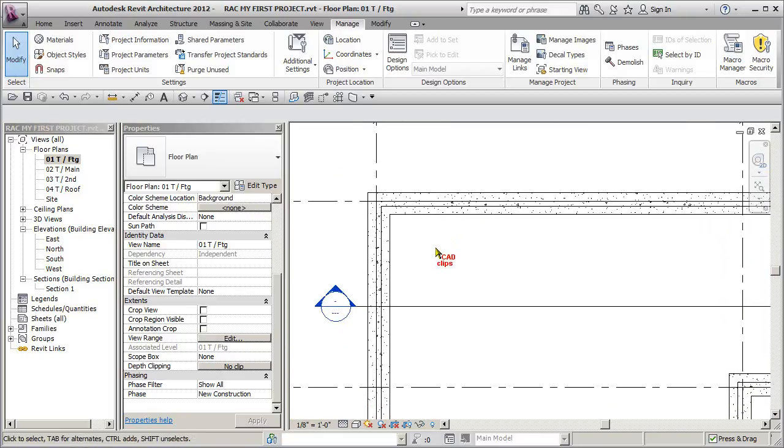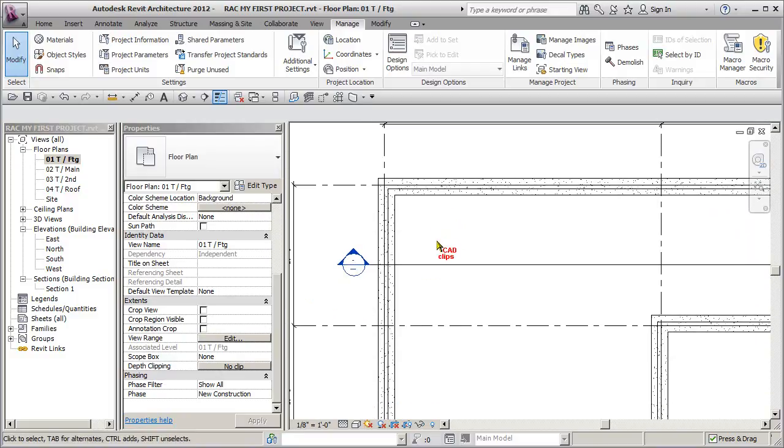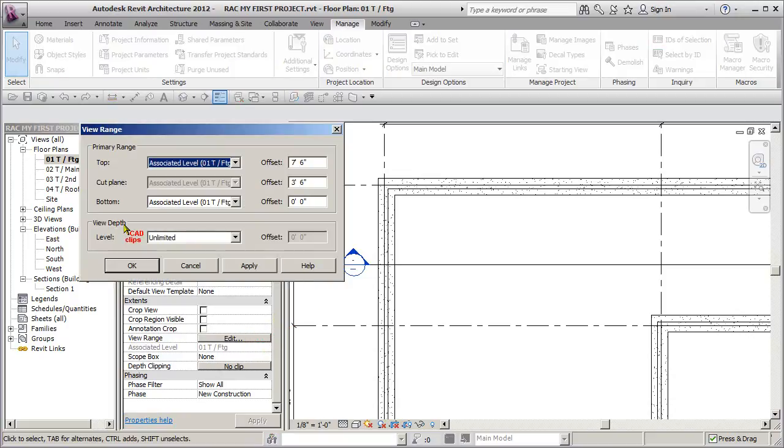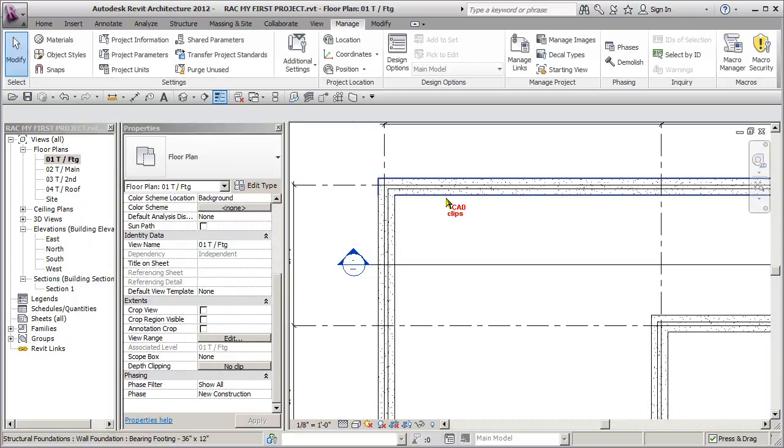The first way we can do it is by controlling it globally with a setting for the line style Beyond. What happens with our view range is that when lines show up in the view depth, which is why these are showing, they take on the line style Beyond. So having said that, hit OK. These lines are showing up and they are considered lines beyond. That's the key, because they're beyond the view range in the lower part.